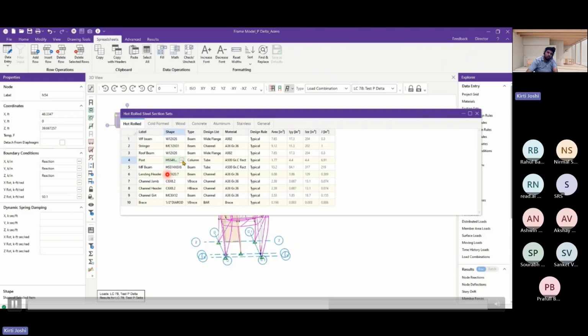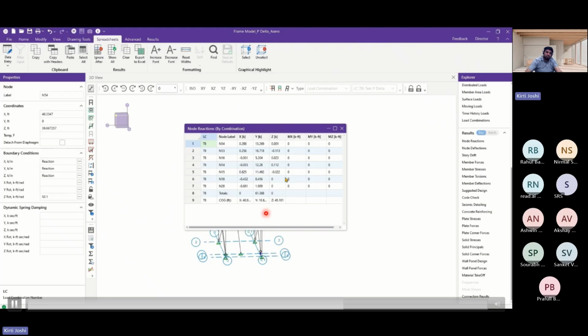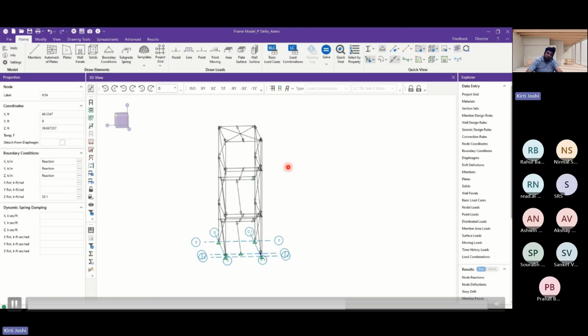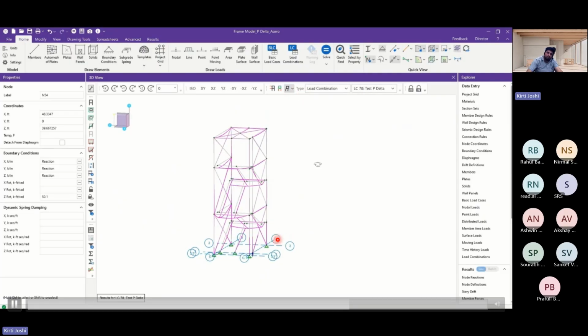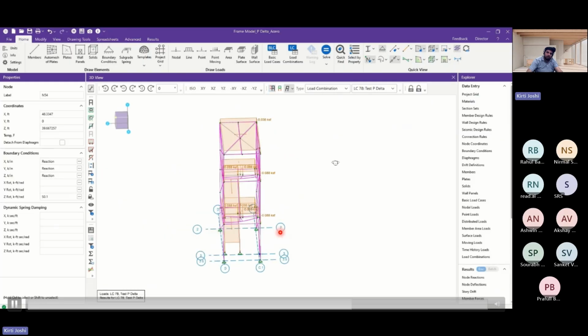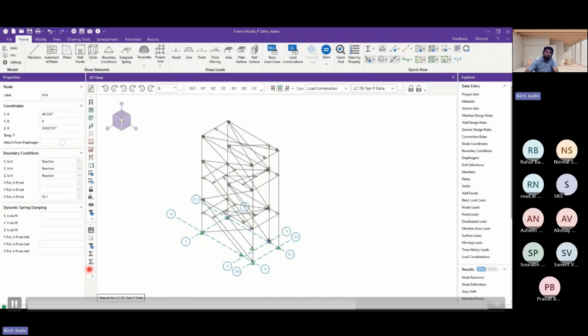So what I will do is try to change the HSS tube size for this column. There are multiple steps to check the P delta convergence, so changing the section property is not the only solution. I have highlighted it: increase the section size because I saw that the column is not stiff enough. Now the issue has been solved for that. I will look at the deflected shape after increasing the size, and the deflected shape looks okay to me. This way, you can deal with the different types of P delta divergence issues.